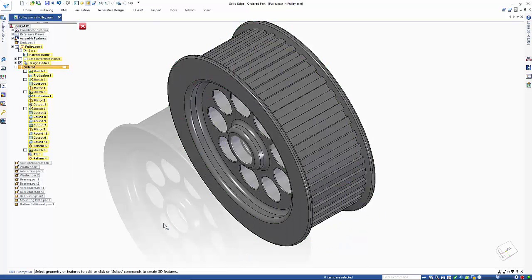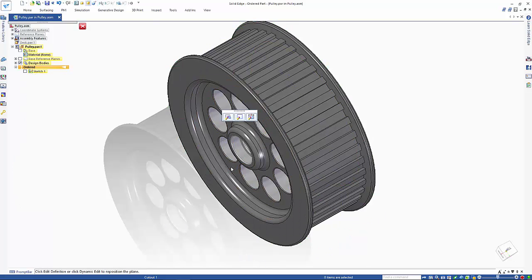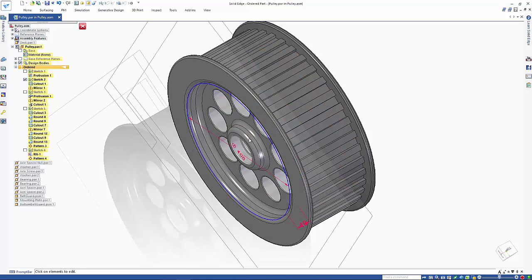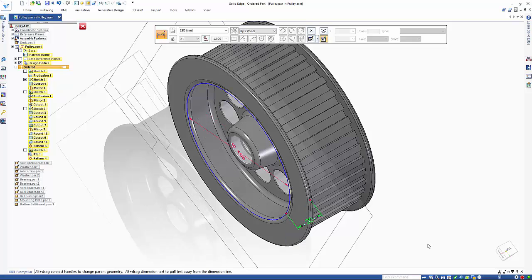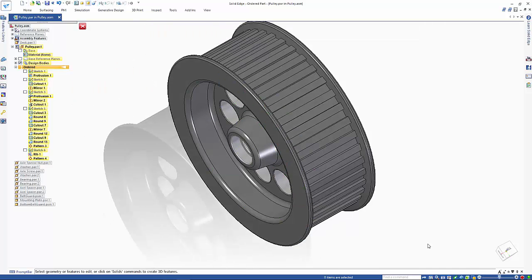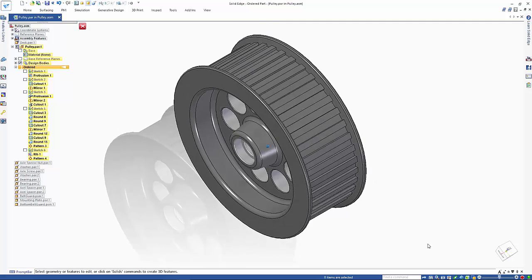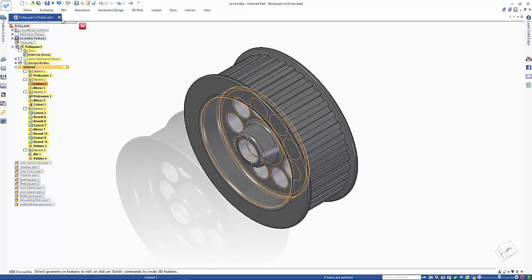This appears as though it worked. But another issue is the thickness of the inner wheel is now too wide. Let's select the feature and push it back from 10 mm to 20 mm. Now those edits were easy, but you do have to figure out which features to change and in what order.